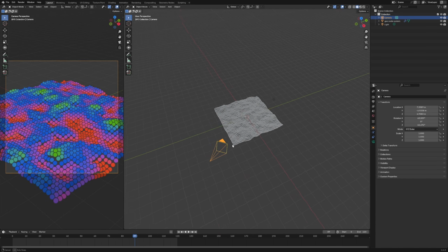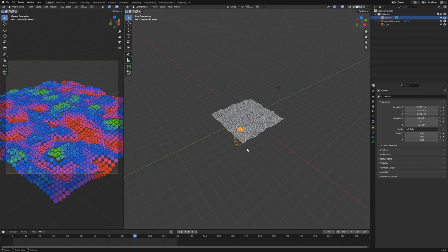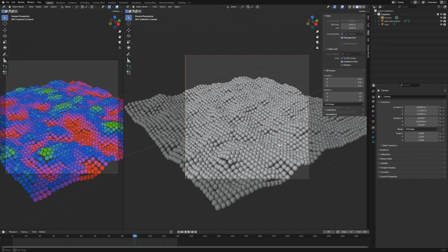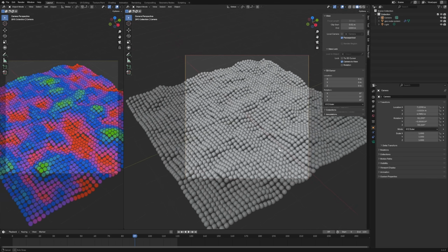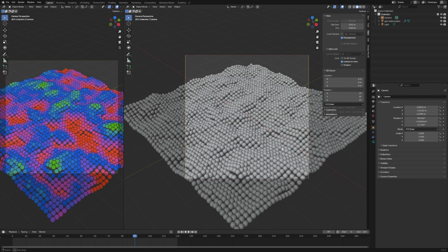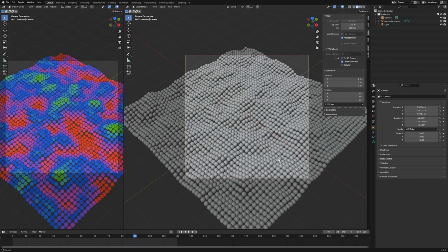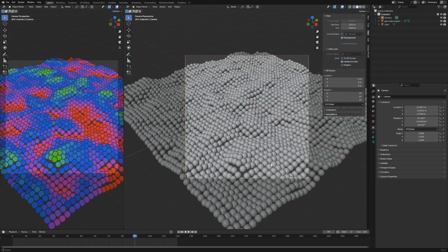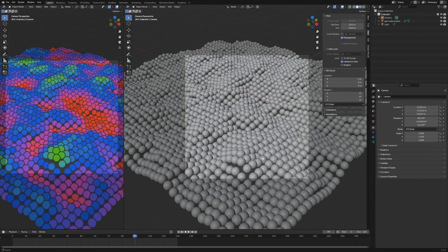And then I think actually we want to tilt the camera a bit more so we can have it view up. So we go on the camera, click the camera, push N. We now have all of these different things. We click view, we go camera to view. So if we go 0 into the camera, we can click and drag and move it like how we normally would in our viewport. So I'm just going to find an angle, something like this. Maybe moving it more down like this so I get a better height view.